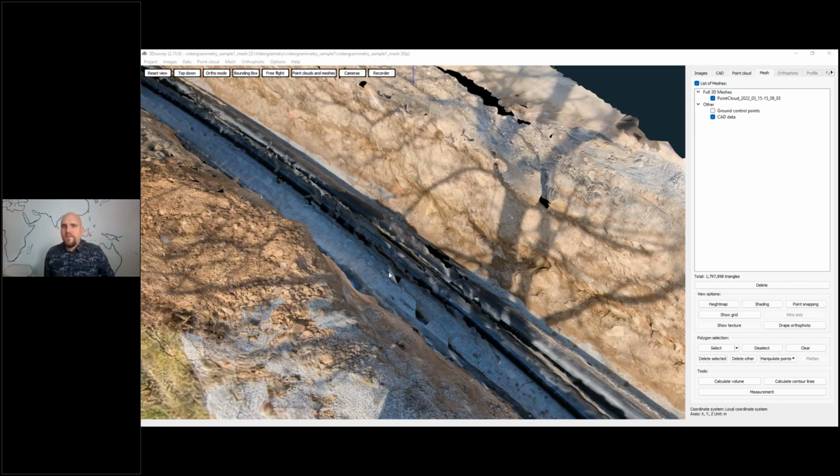And then the rest I would just place at the regular interval between. So then if your area of interest is, for example, larger than 200 meters, then maybe I would use more ground control points. But it shouldn't be necessary to have 50 meters. So having 50 meters between first and second set of points and third and so on, I think 50 meters is plenty.